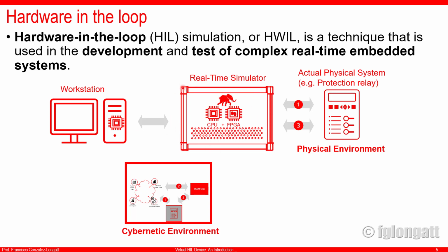Inside this real-time simulator, within a cybernetic environment, we are creating the model of the power system and the WAMPAC that we are developing, and we are sending signals from the real-time simulator to the real physical relay to test the performance. And that is what I am representing over here.